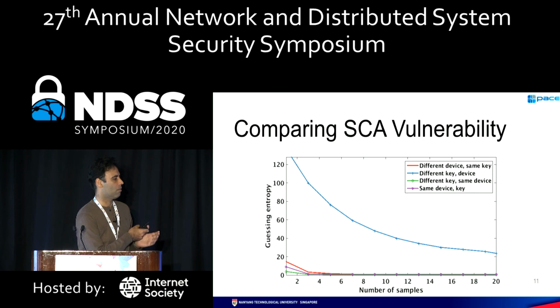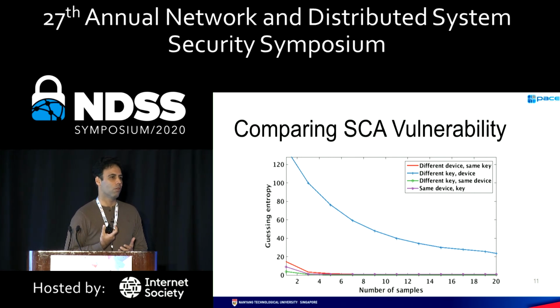Now, when you compare 2 traces to 20 or 200 traces, that might not look that bad, because in terms of measurement, these are only a couple of seconds more. But when we are talking about protected implementations on more recent computer architectures where you have a very low SNR, this problem can be much worse.